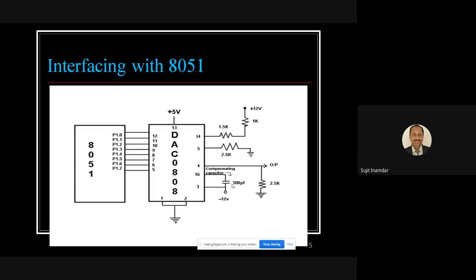Because if by mistake you give more voltage or more current through it, the IC or device can get damaged. So for that, trial and error is required at the primary level. And if you have gone through the detailed design, then you can decide whether to take a 500 pico or a 100 picofarad capacitor. But here, as this simulation part is going on, for our educational purpose it is okay to make a trial and error, and you can construct this circuit diagram in Proteus.